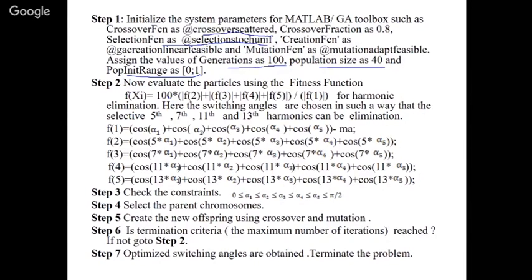And your evaluation function. So f of I, this is nothing but your THD. Okay, so here I took the absolute value. Otherwise it is nothing but the square root of all the F2. What is F2? It is the fifth harmonic. That should be 0. Okay, so here if 0 squared comes, it was the best, so your THD will also be 0. But the fifth harmonic will be a slightly lower value. So you have to take the absolute value of the 7th, 11th, 13th divided by the fundamental. So this is your fitness function.